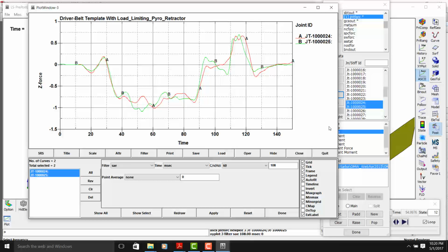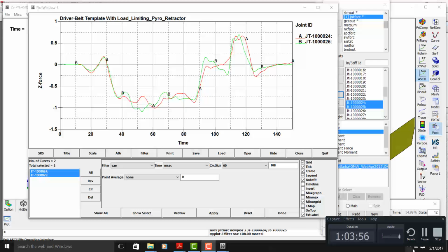So we have done all this. We have done the accelerations of the head, chest, pelvis. We did the chest deflection according to the manual. We did the corrected upper neck moment, which we are interested in, and we have also done the femur forces. So you get the idea of how to do all this. If you now follow the dummy document and plot everything, you will get everything you are interested in. So that brings us to the end of workshop 4.